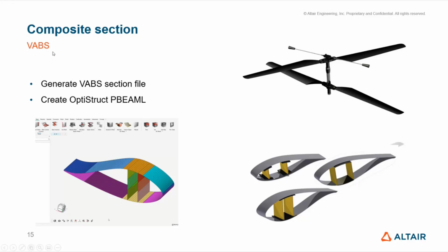So for those not familiar with VAPs, it's really popular, and even outside of aero now, for all of this new mobility, there is a huge trend to model such blades or wing box by a 1D element with a section cut, because it will allow an accurate representation of the 1D slender structure dynamics,